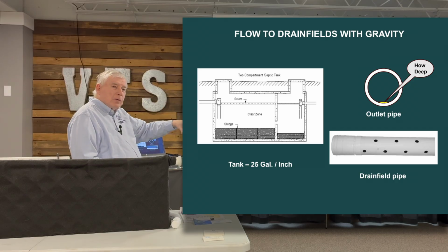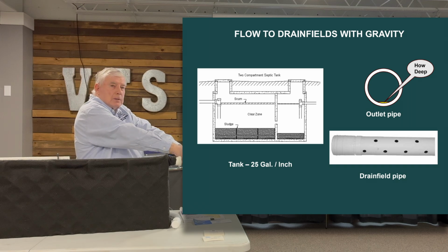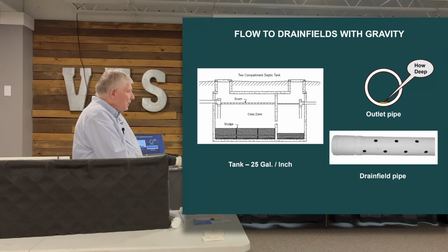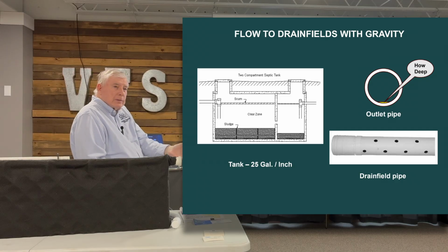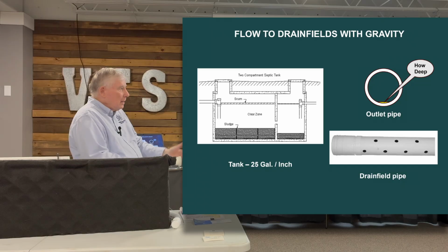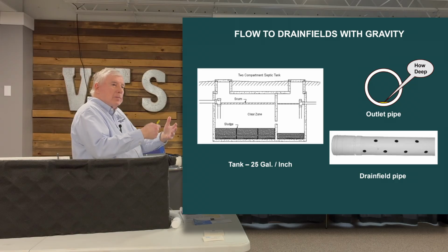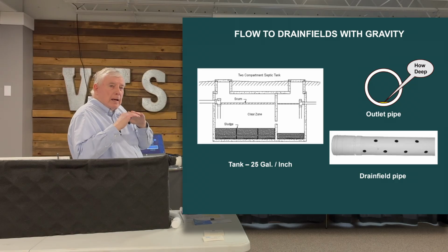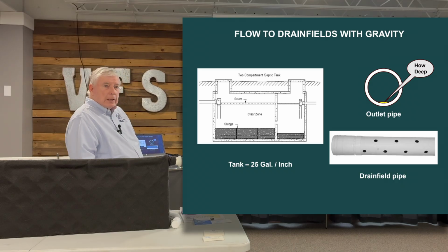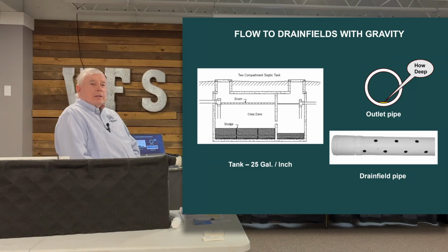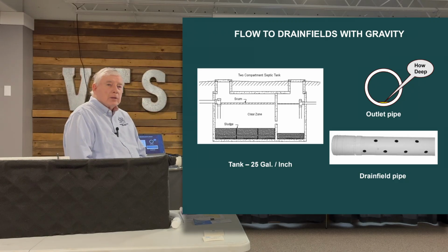1.6 gallons to find a hole before it all goes out into the stone? I don't know the magic number, but these are generally 3/8 to 1/2 inch holes in a perforated pipe. And once it finds a hole, all that water could be going out 1 or 2 holes. And there have been some recent tests and demonstrations shown on that actual thing. So how much of that drain field gets used for the first year, or the first 5 years, or 10 years? Next to none, right?